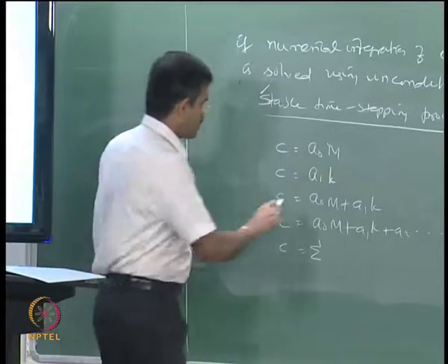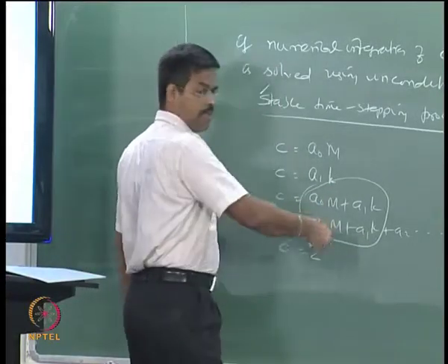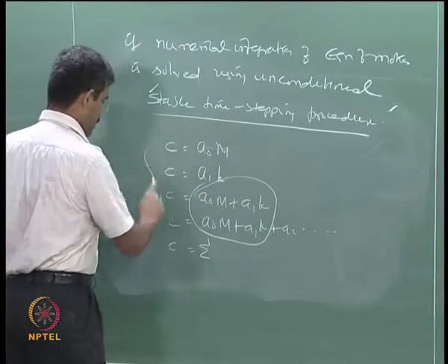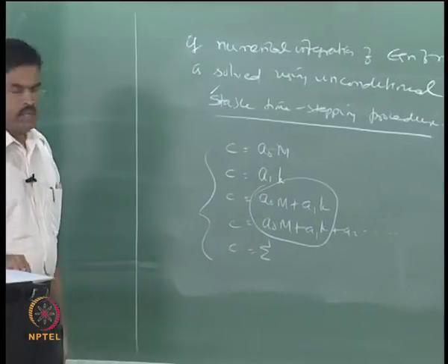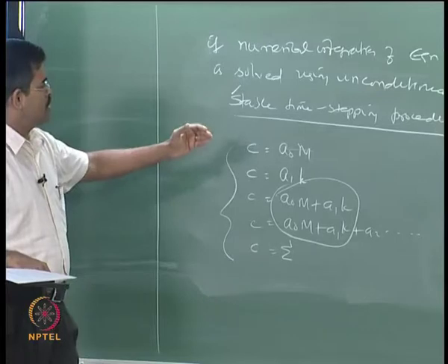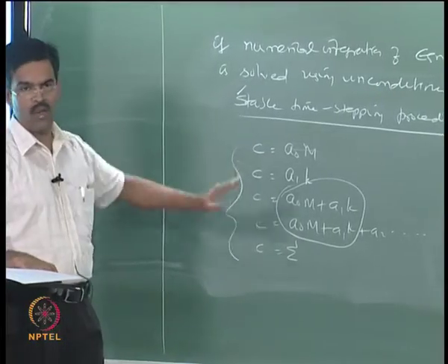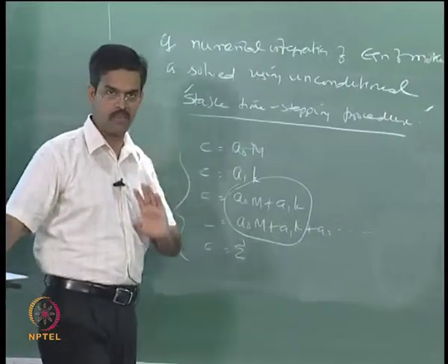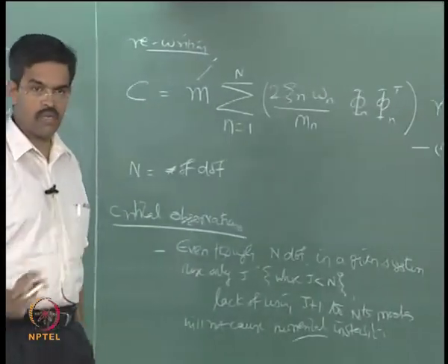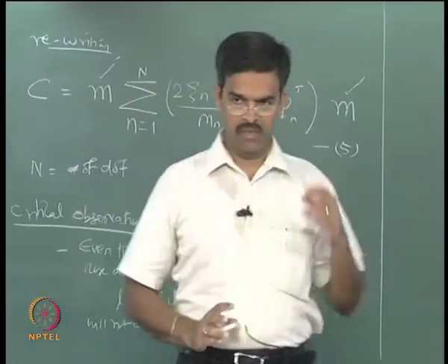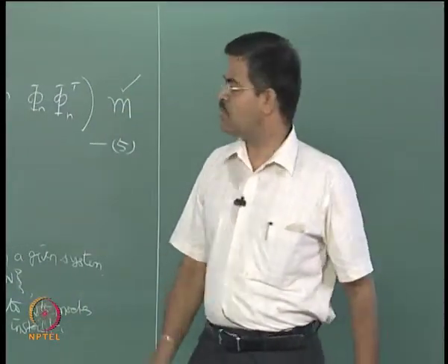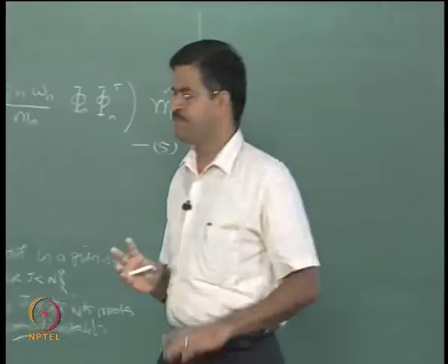This is also a part of Rayleigh, both are Rayleigh. This is Caughey, this is Rayleigh, this is classical, all are classical damping. They have got different applicabilities. So, we cannot compare all of them. There is no question that I will get the same matrix by employing different techniques. Please remember this. These are not different methods of finding or comparing C. You will never get the same C by all the methods, never. Okay. These are different procedures to get C.